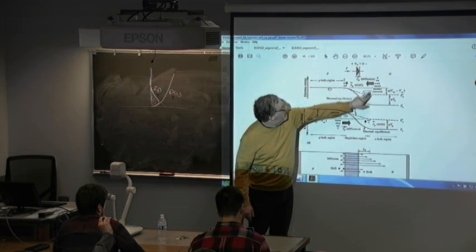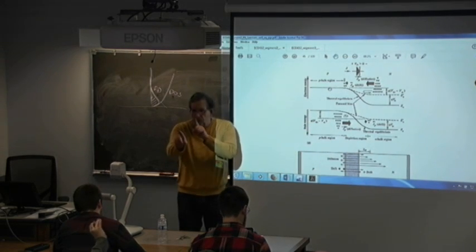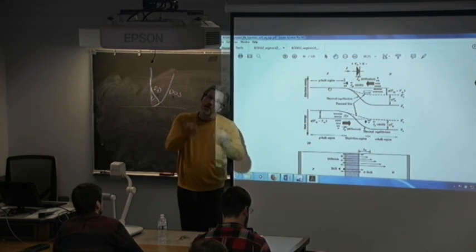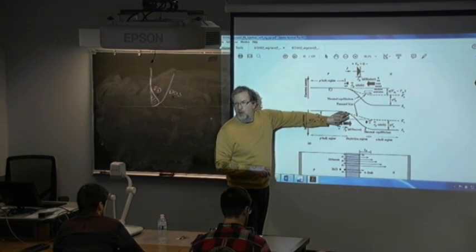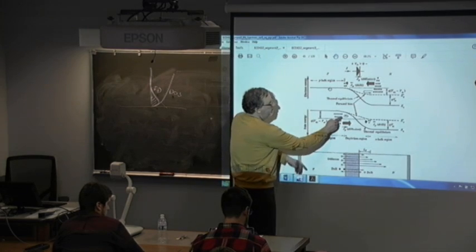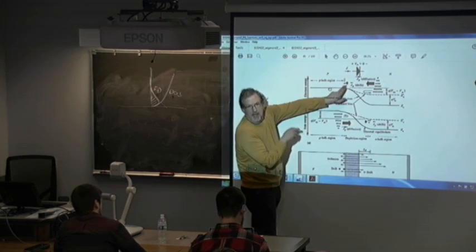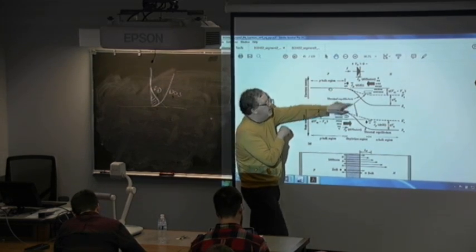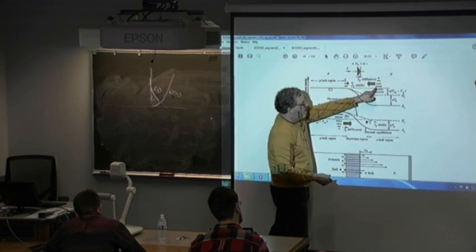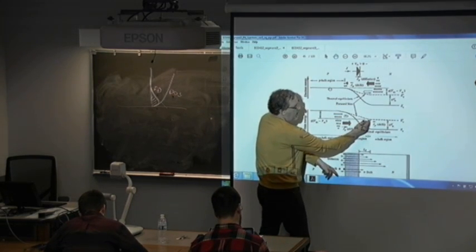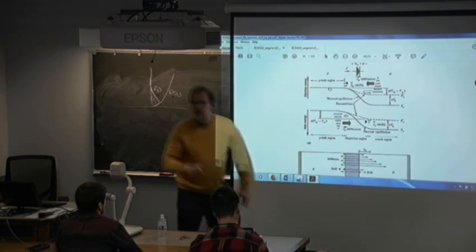And then these guys here. Now, thermal generation, hold on a second. Generation is a 2-carrier event, right? So when I create electrons, I'm also creating holes, right? But adding a few holes to this side is not really of consequence. So it's the electrons, the minority carrier electrons. But I can also have generation happening here, pushing an electron up, and so therefore I'm creating holes near this diffusion length.